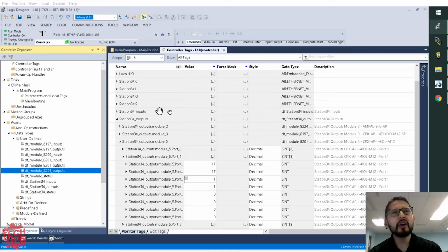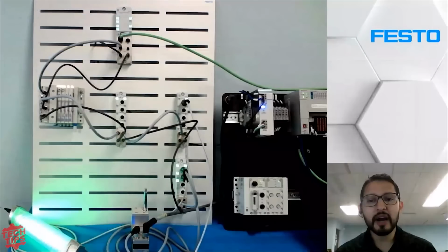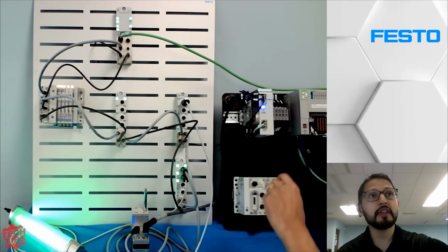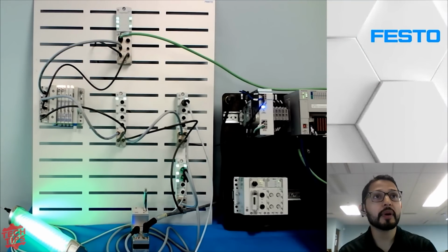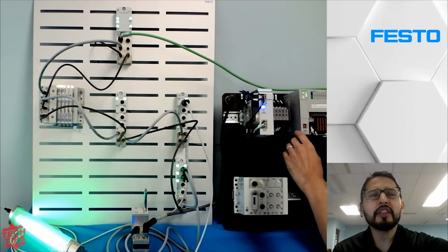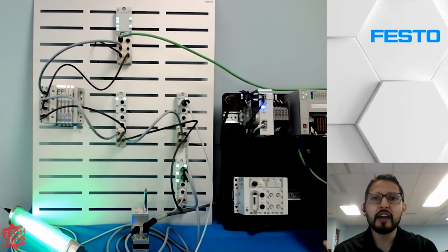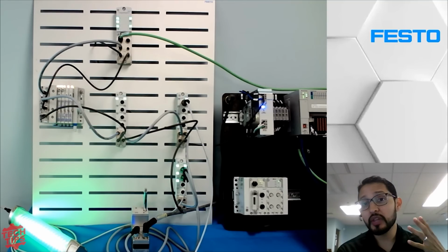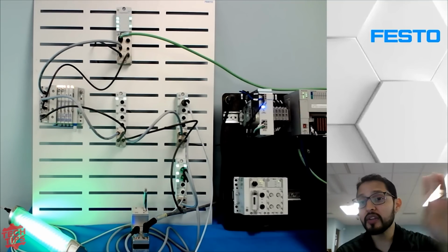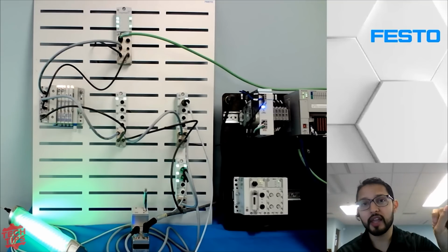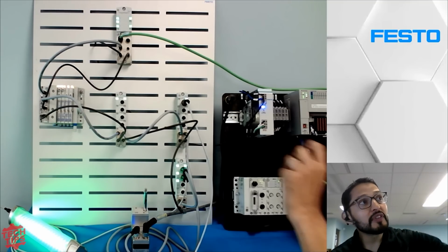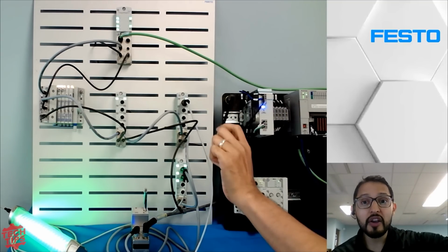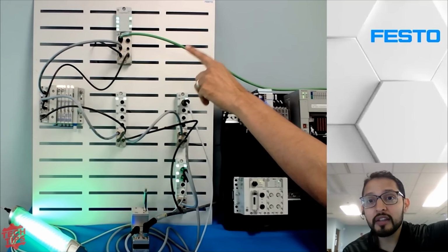No, I think the only other thing that I missed mentioning is, in my current configuration, I mentioned at the beginning that I'm using an L18, a Compact Logix. Depending on which PLCs you're using, they have different capacity for how many Ethernet IP nodes you can connect to it. In my case, I have only 4 available connections because of the model that I have. So the benefit of using something like this, some distributed I/O, is that I'm only consuming one Ethernet IP